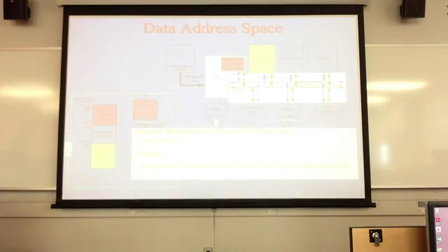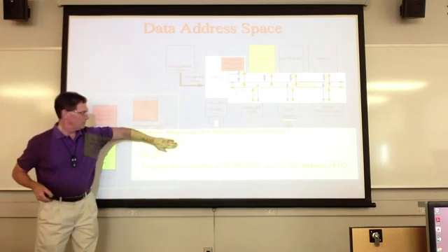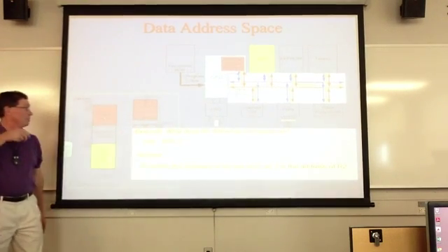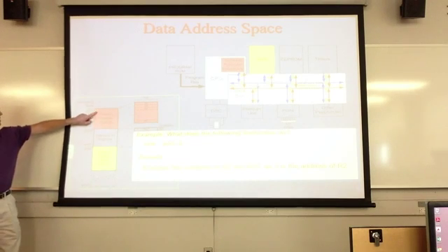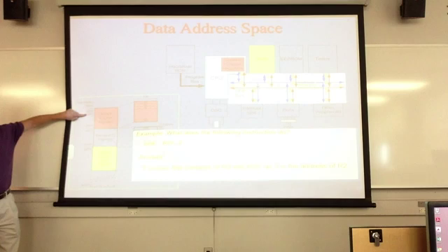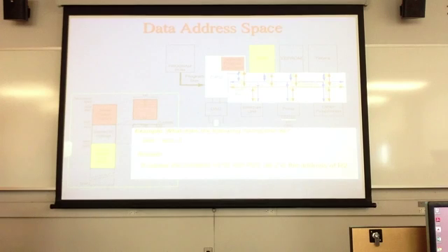If I just take this one, we're going to load to R20. It copies the contents of R2, because where is that memory location sitting? Where is this guy sitting? Right here. That 2. It's in data memory, but where is it? It's taking the contents of that general purpose register, which is sitting in R2. This memory location right here is R0. That memory location is R1. And then if I load a 0002, it's going to copy the contents of register R2 into R20. All right, store 53 into, now this is called the stack pointer high.